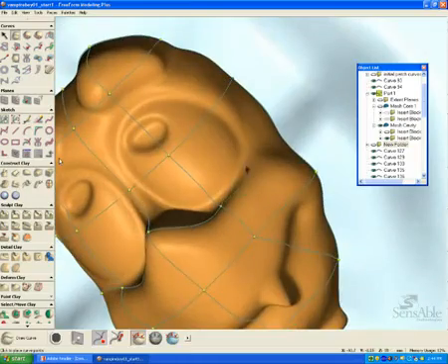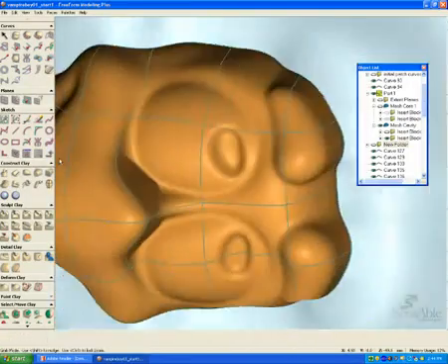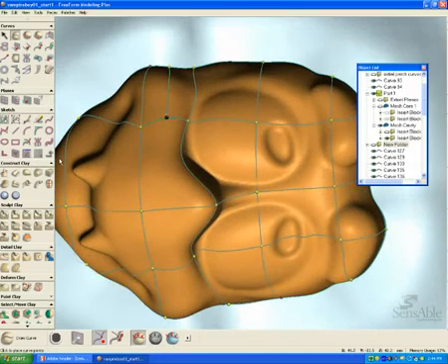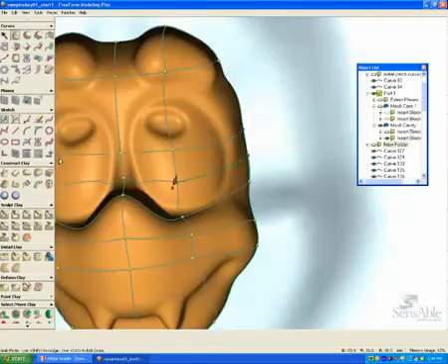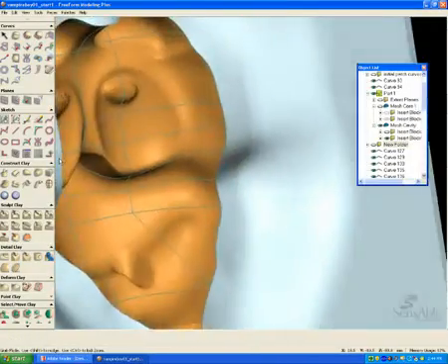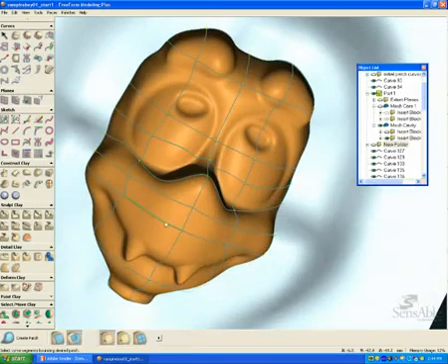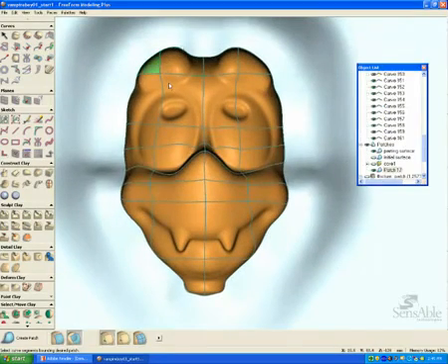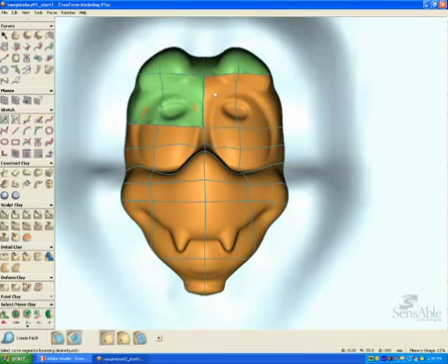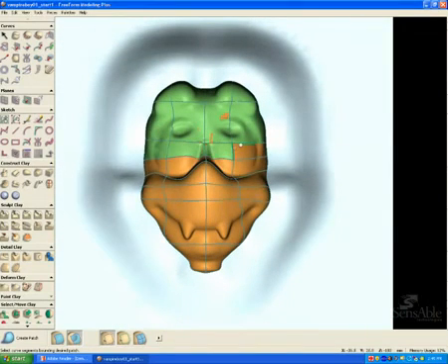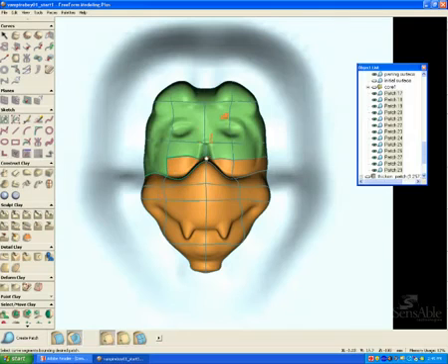You can do it this way by creating these NURBS patches and exporting the whole piece as one, or since it is a mesh already, as long as the clay resolution was very high when you were creating it. If it wasn't, you could just bump up that resolution anyways. As long as you have a decent resolution clay piece before you make the mesh, you can just export this orange mesh the way it is as an STL. And when you import the STL cavity and the IGES or STEP NURBS file parting surface, you can import both of those as separate files into a CAM program for milling, and they will intersect perfectly anyways.